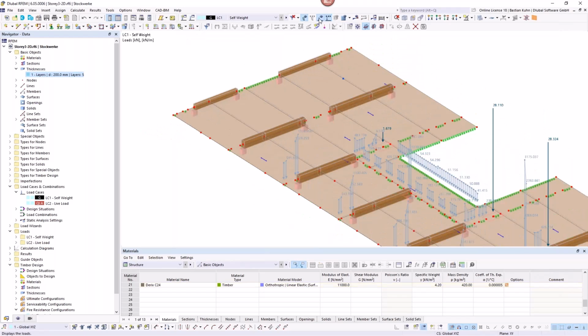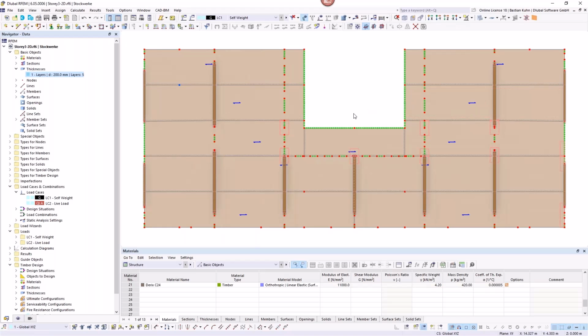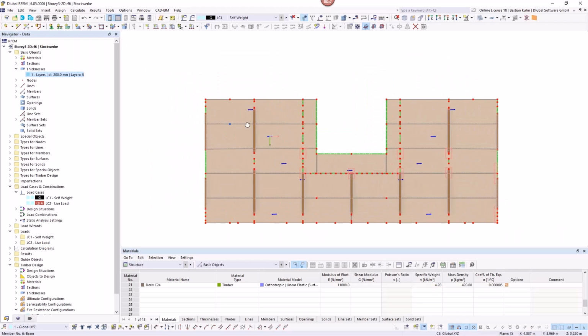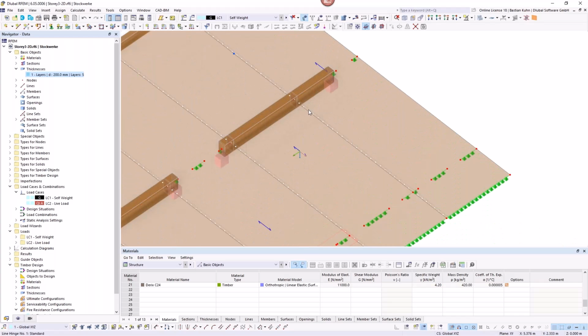There's nothing so fancy and new. But now when I'm working as a designer and constructing it, you probably realized already the blue arrows here. It was in previous versions always hard to know how I'm assigning the plates. If we look at the downstand beams that I have underneath those plates in here, you see that there's a downstand beam that is supporting this plate and this plate and this.